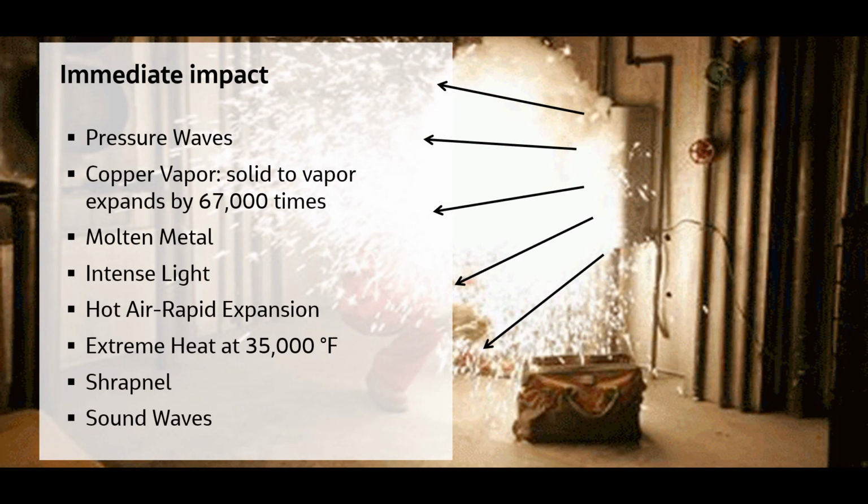Imagine this. During a severe arc flash incident, within the span of milliseconds, there is a lot of stuff coming out from that electrical enclosure. There are blast pressure waves at 140 decibels that can throw workers or operators across rooms. There is molten metal shooting at speeds exceeding 700 miles per hour and propelled up to 10 feet. Basically, there is a sudden and severe impact from light, sound, pressure, heat, and metal. And a lot of this is actually avoidable.